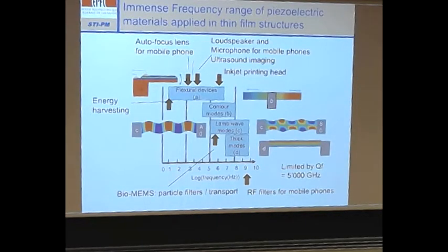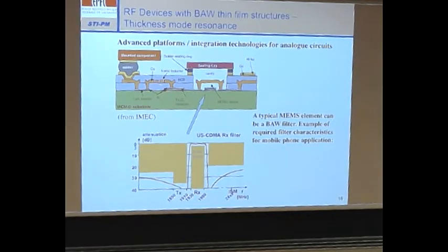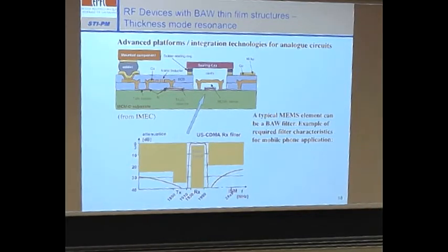About applications: inkjet printing heads. This is also on the market now. Here I would like to point out that many of the advantages come not only from the silicon MEMS chip having made a lot of advancements. What has also made a lot of advances is the packaging. Nowadays you can mount a package on top of a silicon chip, silicon package and so on, so that everything becomes more and more closed.